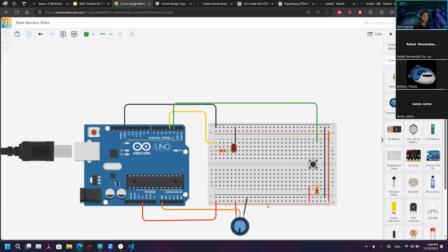In more advanced coding, you'd probably make it an interrupt so that when you press the button, it interrupts whatever the Arduino is doing. That way it'll definitely read your input. But for now, the way it is, the delays basically stop the program from running for a bit, so it doesn't read when you're pressing the button. That's what's happening.